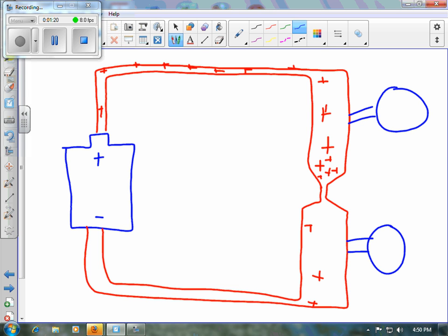So let's say this side is going to measure 10 psi, for example. What do you think roughly the other side would be measuring? Anybody have a guess? It's on the negative side of your pump. The negative side is sucking these things back in. Would it be a negative pressure? Or zero. Or zero? Yeah. Just call it zero. 0 psi. Okay, so that's zero pressure. So there's a pressure drop from here to here.